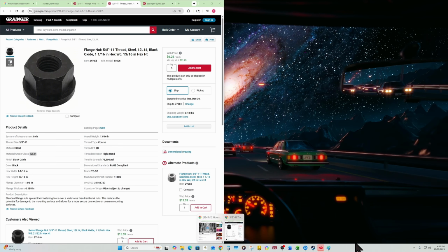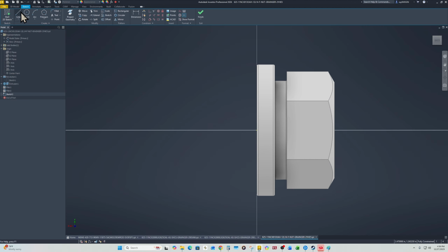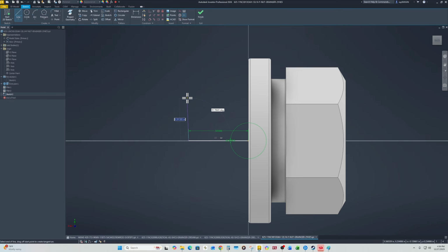Then we need a thread. So let's start a 2D sketch on the origin, and then select one of these two. It doesn't really matter which one it is. Select this one and do line, tab 0, tab 0, tab enter. Then I'm going to make it to the left this time, or I don't even know which side I made it, the other one. So I'm going to do 0.5 tab and then 0 degrees, tab enter. Then I'm going to draw the little template again. 0.25 tab 9 tab enter.